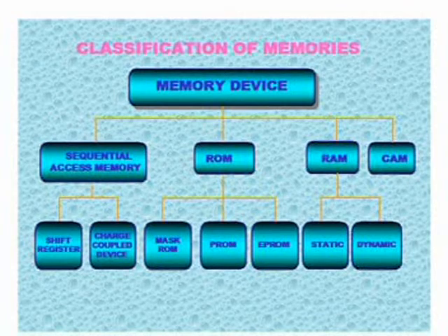The next type is the random access memory. This is also called read-write memory. The main difference between the sequential access memory and the random access memory is that in the sequential access memory, we are reading or writing the data in a sequential manner. So the time taken for each memory location will be different. But in this case, we can randomly choose the data. So the time taken for each memory location will be the same in the random access memory.